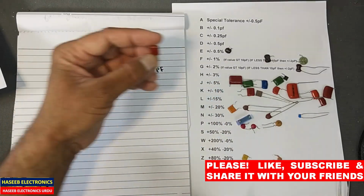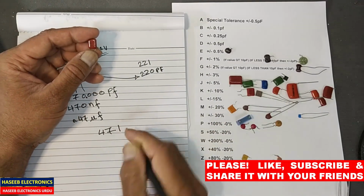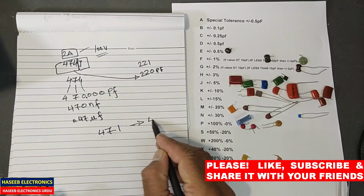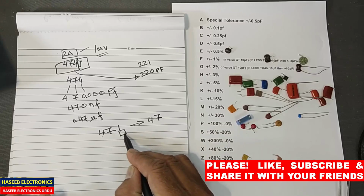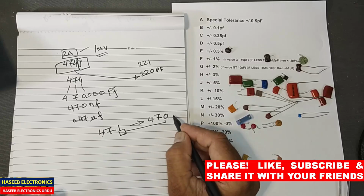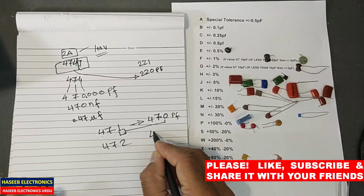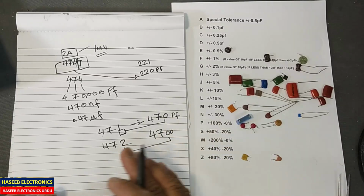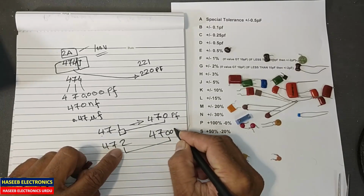If it is 471, that means 4, 7, and this is the multiplier, number of zeros. 1 means 10, so 470 picofarad. If it is 472, 47, then these 2 zeros. Very simple. It is called the multiplier digit. So it is 4700 picofarad.